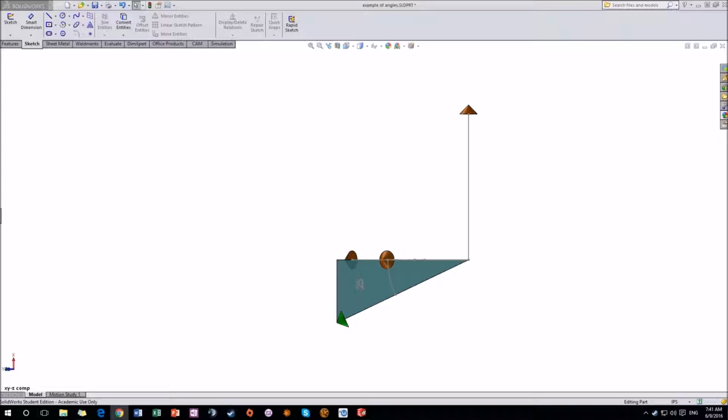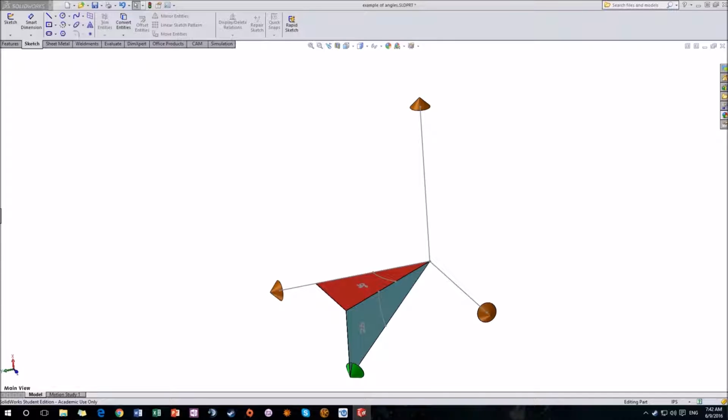It will be the hypotenuse, the force in this case, times the sine of the angle of 25 degrees. To find the other leg would be the hypotenuse times the cosine of that angle. Now you might be curious why the other leg of the triangle is important. Well, when we go out to the main view again, we can see that that leg is actually the hypotenuse of the red triangle. That means that when we are wanting to get our x and y components and values, we're going to need that leg because it becomes the new hypotenuse.